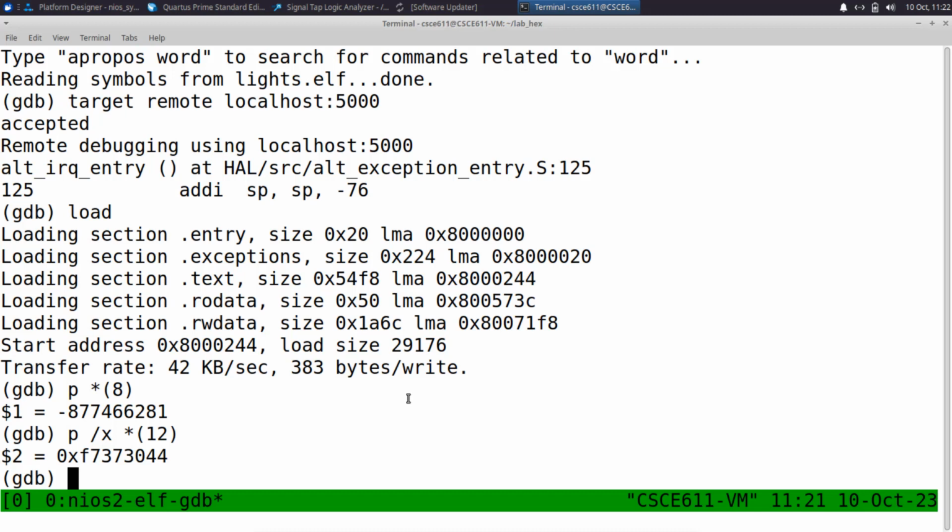So it works. Now, if there's a bug in there, you would be able to debug it doing this kind of testing. Unfortunately, I ran out of time. I wanted to write some software that did 2 consecutive reads, but I'll just give you a spoiler. I did this in my office, and I wrote a loop, actually not even a loop. In my Nios code, I had 2 reads in 2 lines of code. Then I looked at Signal Tap, and it was 7 cycles. So 2 consecutive reads from the software were separated by 7 cycles.